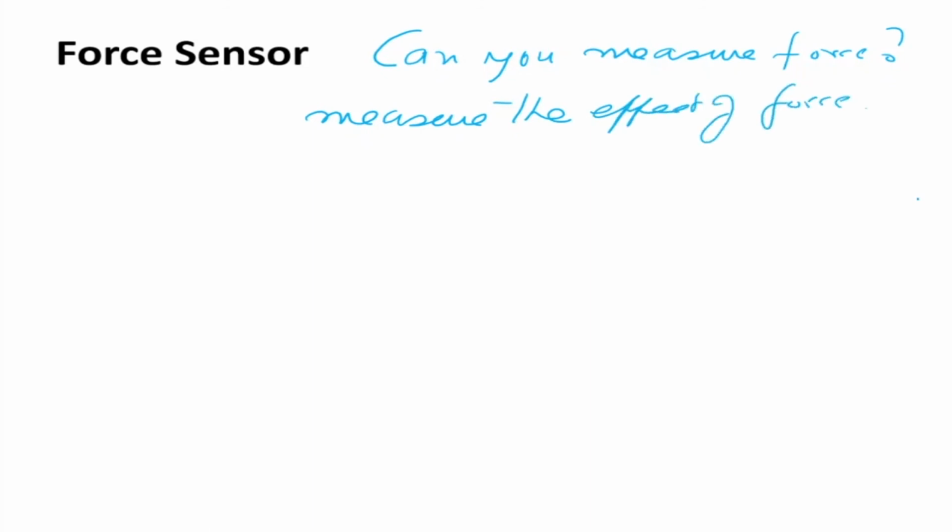Okay, so first of all, can you measure force? Can you apply force? These are interesting questions. In air, you cannot apply force, neither can you measure force. If you apply force, there must be an equal and opposite reaction; only then can you apply force, otherwise you can't. So if you measure force, you are basically measuring the effect of force. You are basically measuring strain.